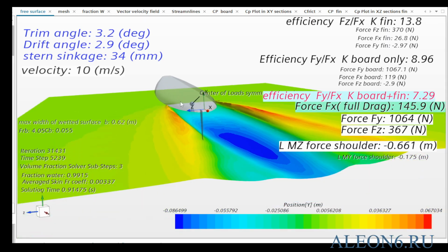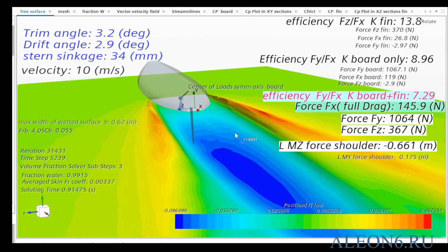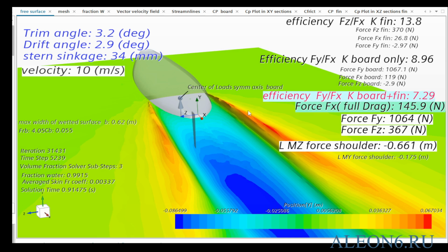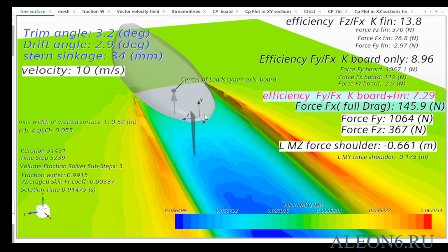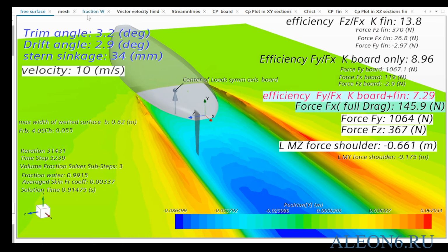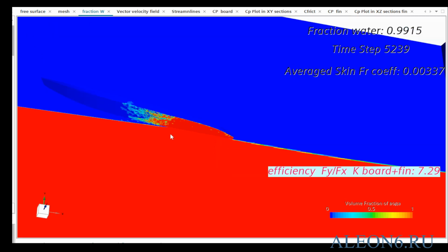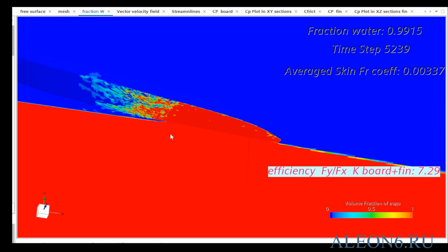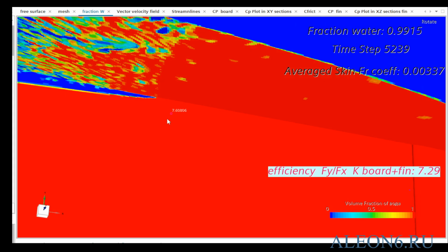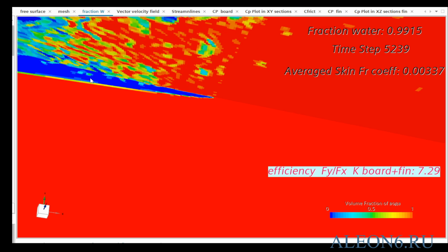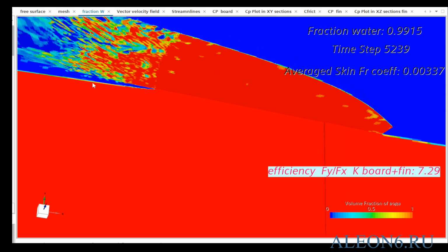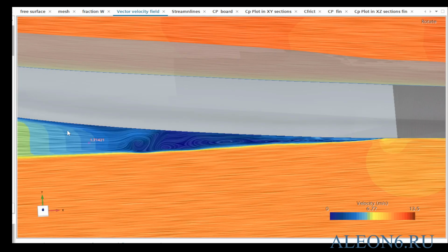For example, we get the following picture of a wake behind the board and two crests extending from the sides of the board. The board is moving on a port tack. A small fin wake is also visible. This image shows the water-air fraction generated by the solvers. At this point, flow backup occurs because our bottom is flat. A thin stream strikes forward, then some semi-streams of droplets with a mixed fraction form, disturbing the free surface from the front. Such a picture is produced by CFD.